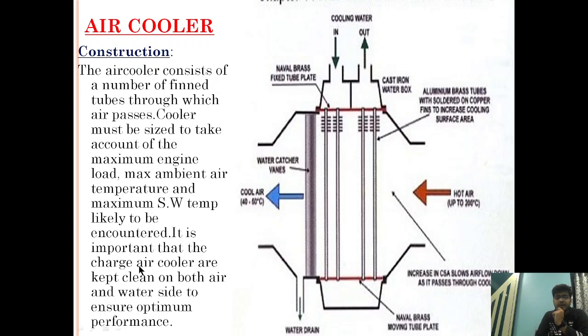It is important that a charged air cooler is kept clean on both the air and water side to ensure optimum performance. So it is very important that maintenance and cleaning be carried out at regular intervals of time.